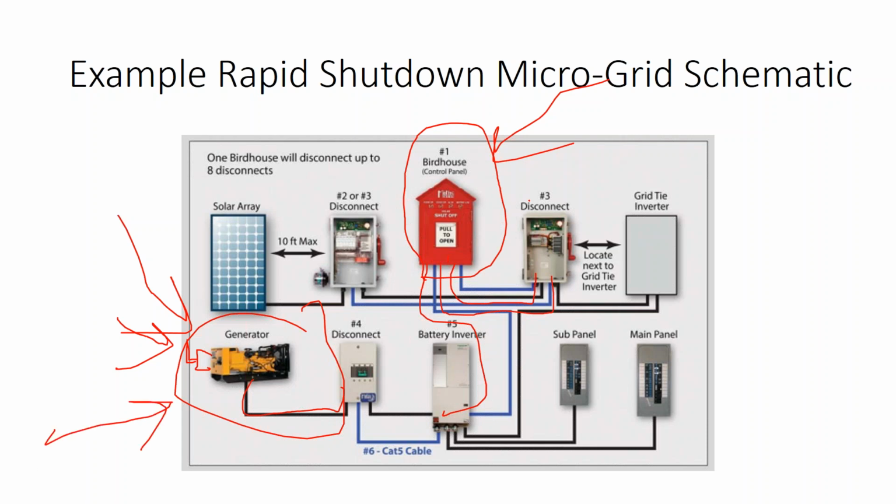And so what that means is, if you want to have a system level disconnect outside the building, it has to be physically separate from the other disconnect switch that you already have for your solar array. So it will be a code violation if you put a disconnect for the battery system, for the backup system, right next to your solar array disconnect. That solar array disconnect is not part of code. It's a little confusing.